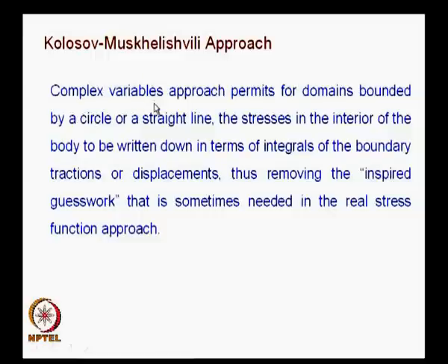and what is the advantage is this approach permits for domains bounded by a circle or a straight line, the stresses in the interior of the body to be written down in terms of integrals of the boundary tractions or displacements. That is a key point.